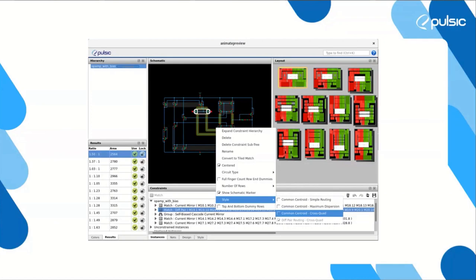You can say, actually, I don't care about symmetrical layout, just try and make it as small as you can. And you can do other things like setting pin sides. So you can say the input pins are on the left and the output pins are on the right, or whatever you like, or on the north or the south. So yes, you can control the type of layout that it's producing, like pin direction, etc.